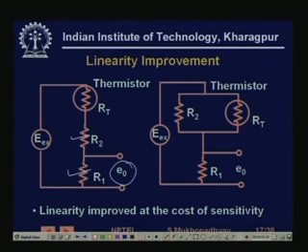So based on linear variation you choose the values of R1 R2 such that you get the E0 values on a linear curve for this thermistor. Then over that range it is expected to be roughly linear.